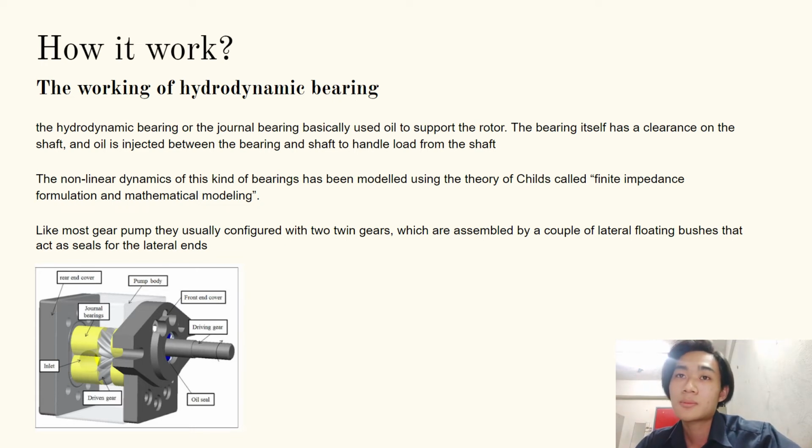For more detail, when the gear is rotating, the control volume's pressure increases to push the fluid to the high pressure chamber. When the gear teeth are in the meshing zone, fluid is squeezed out from each gap of the tooth by the mating tooth. When two tooth pairs contact, trapped volume is generated. This may cause a positive pressure peak and the onset of cavitation. On the intake side, the gear teeth are coming out of the mesh, and the volume of the control volume increases so that fluid is drawn into the tooth gap. The process repeats itself with each revolution of the pump and therefore displaces fluid at a rate proportional to the pump speed.